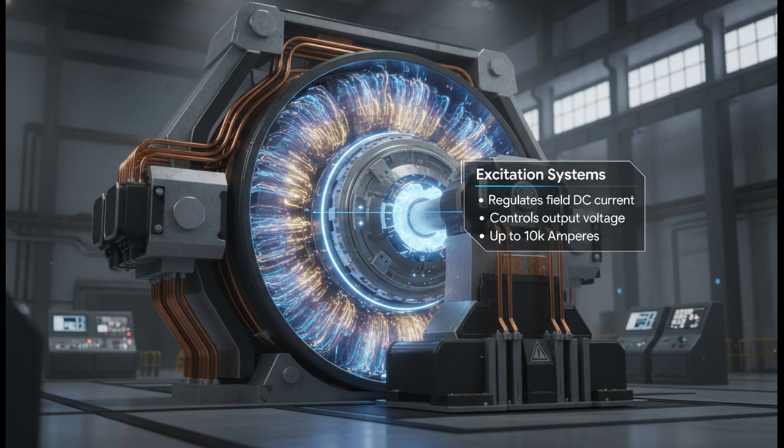But, well, here's the catch. To create the massive, city-powering magnetic fields that we need for modern grids, permanent magnets just aren't going to cut it. They aren't strong enough. So we have to use electromagnets. And this is exactly where excitation systems come into play. These systems essentially pump a highly regulated DC current directly into the field winding to create a truly gigantic magnetic field. By controlling this DC current, prime movers, we're talking massive wind turbines, hydro dams, steam turbines, can precisely control the megawatt load and the output voltage of the generator. And these exciters can be rotating systems mounted right on the shaft or static systems capable of handling up to 10,000 amps of current. That's a whole lot of power.